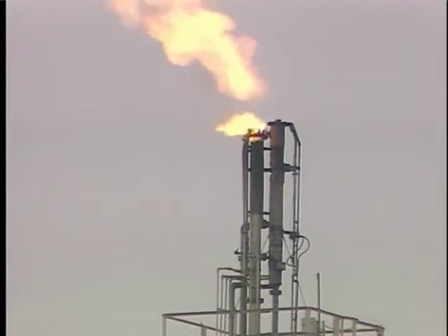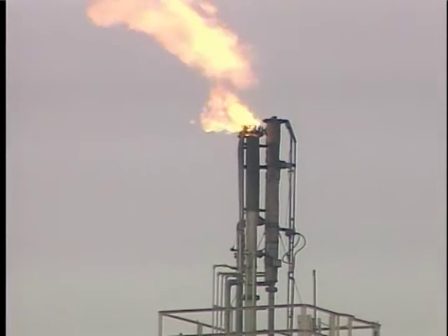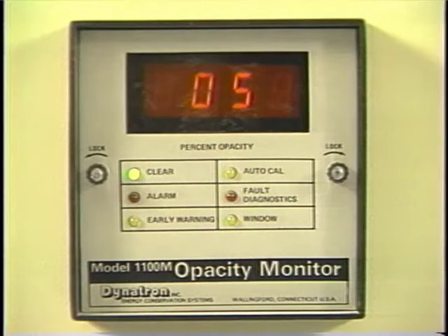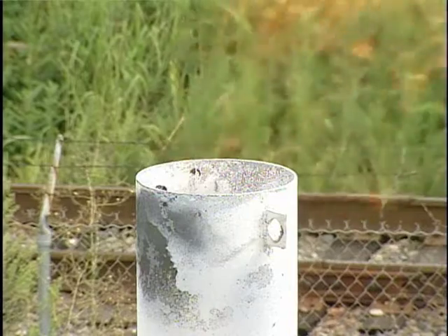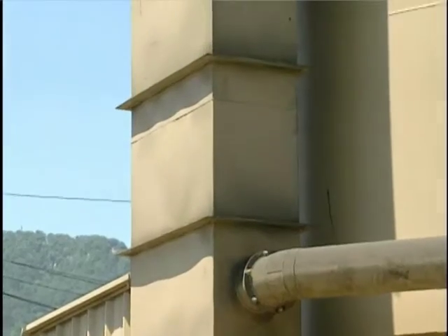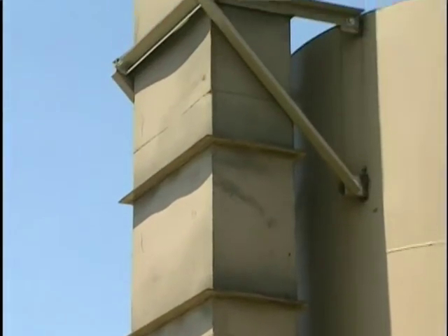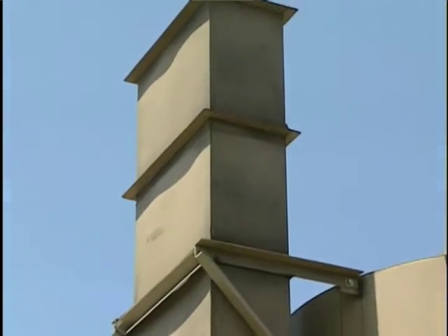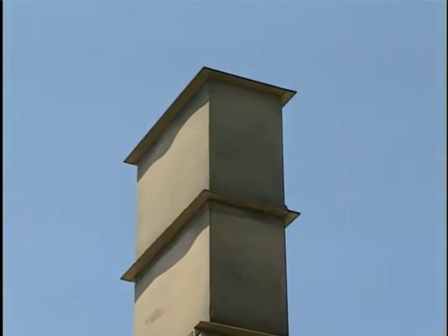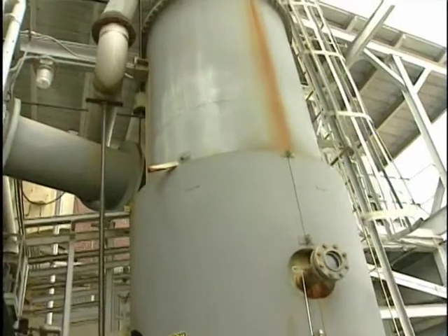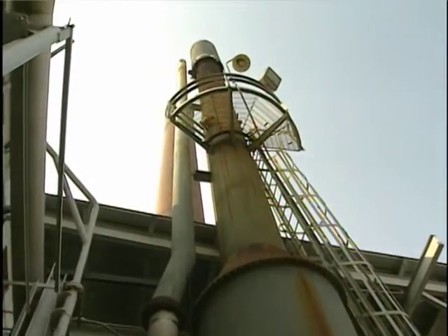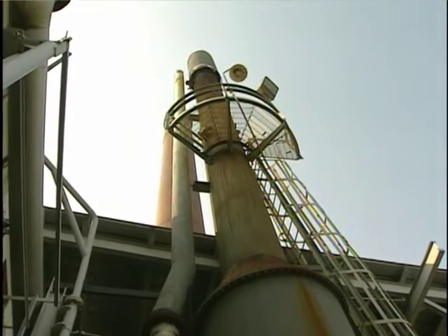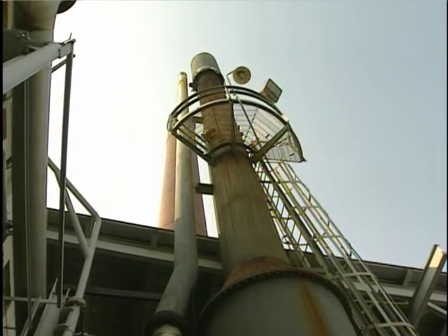Even though incinerators handle gases that cannot generally be seen, stack opacity is still a useful inspection parameter. Visible emissions are caused by non-combustible particles in the waste gas stream, soot generated by improperly operating burners, and nucleation of pollutants generated in the incinerator. The presence of a soot plume indicates severe burner firing problems. This can lead to fouling of the heat exchanger and, in extreme cases, reduced temperature in the incinerator.